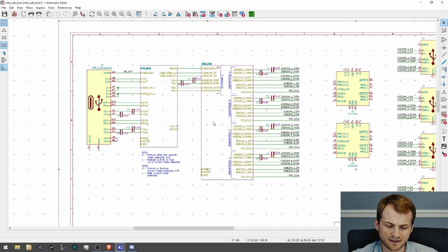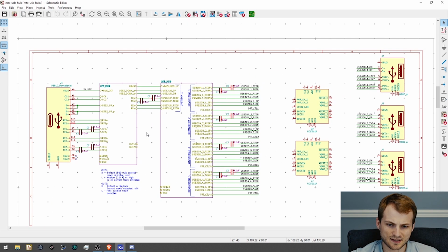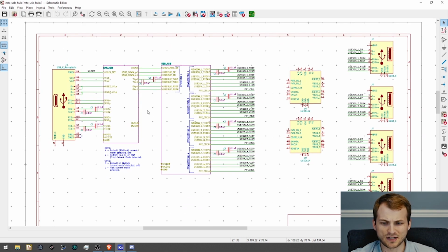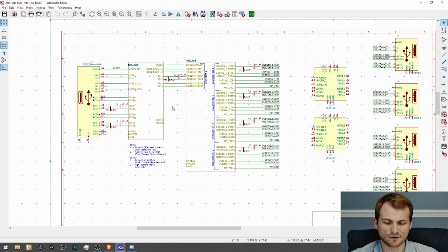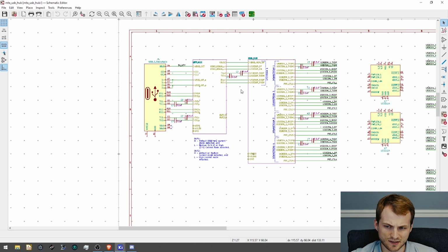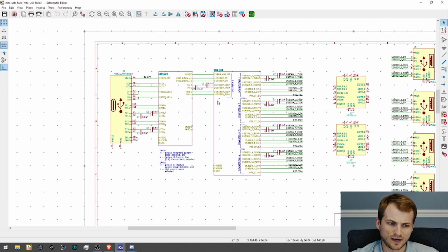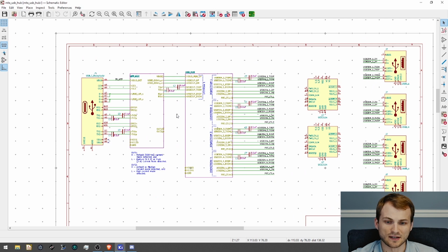So basically, and this is new to me in the last maybe 3 or 4 designs that I've done, I never used to use hierarchical sheets, or I would only use them for blocks that repeated over and over again, because that is the obvious use case. But I've started using them on pretty much any intricate design, because it really abstracts out a lot of the nitty gritty of the inner workings. So my whole goal when using hierarchical sheets is to abstract out anything that's not useful for the overall picture of the design.